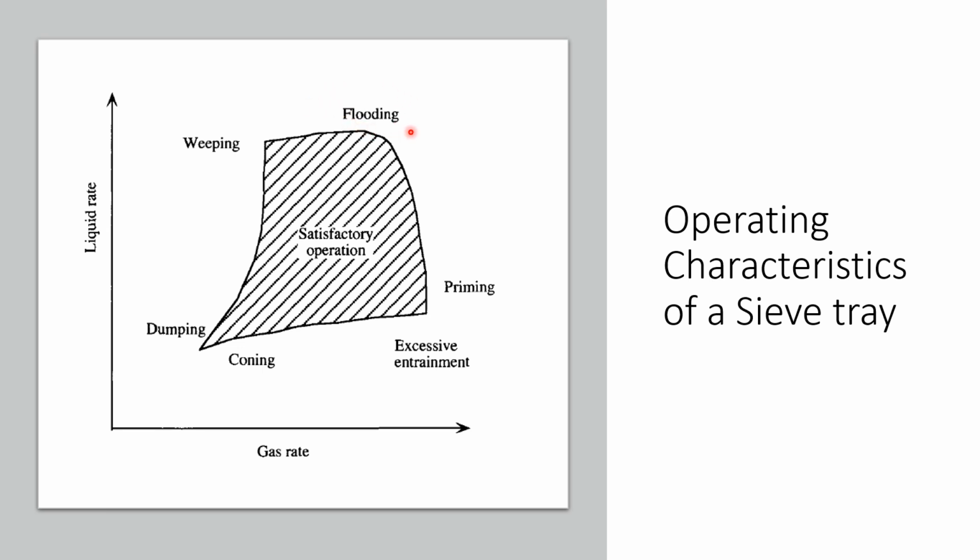So again, as a reminder in terms of design constraint, in chapter 3 we were saying that in an absorption process, in order to decrease the number of stages, we need to increase the solvent flow rate. By decreasing the number of stages, we will reduce the overall height of the column.